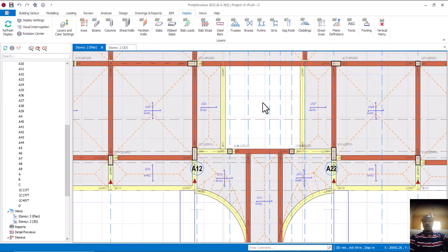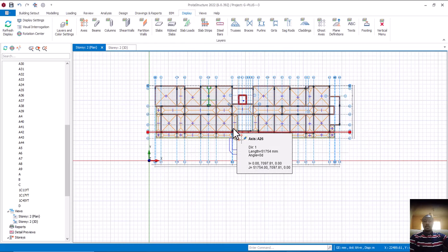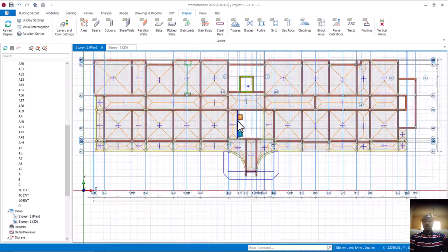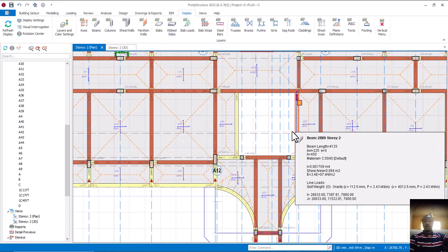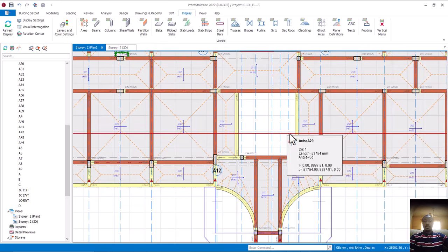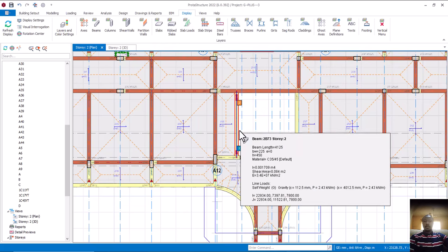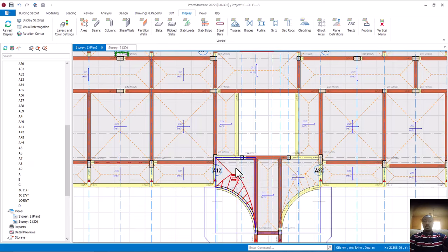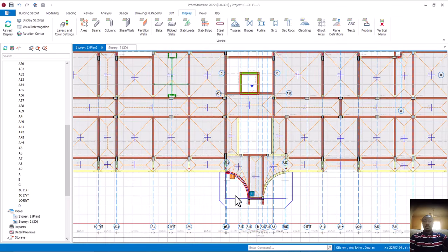There's need for handrail. You can put the handrail wall there. Is that okay? We can calculate it. All right, so that is that. Even without the loading it, automatically it will carry the handrail. The handrail is not that too much, but at least for design sake, you can put a small load there. Like maybe say, let's say 1 course of block, or yes, maximum of 1 course of block. It's okay. And you know how to calculate that, isn't it?